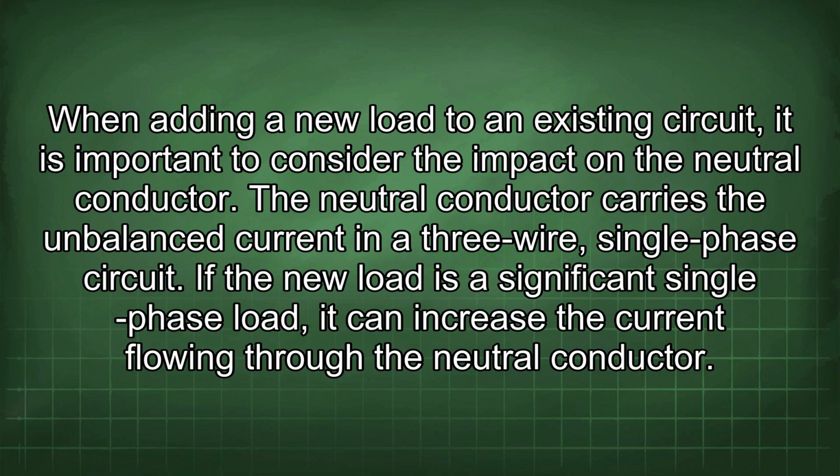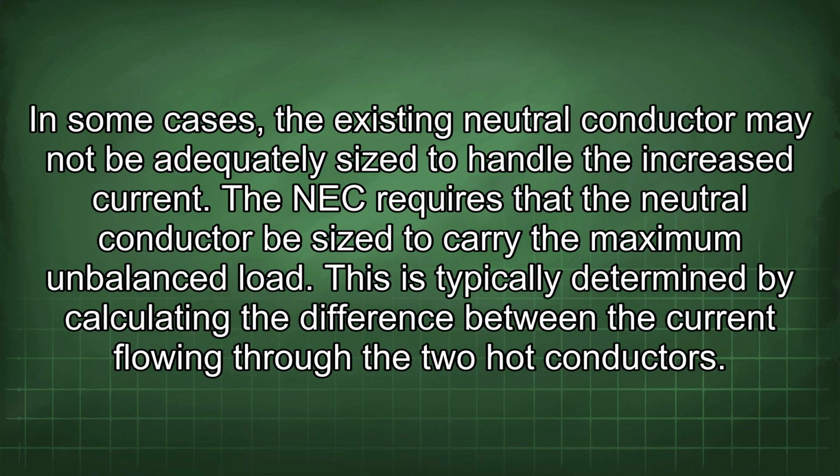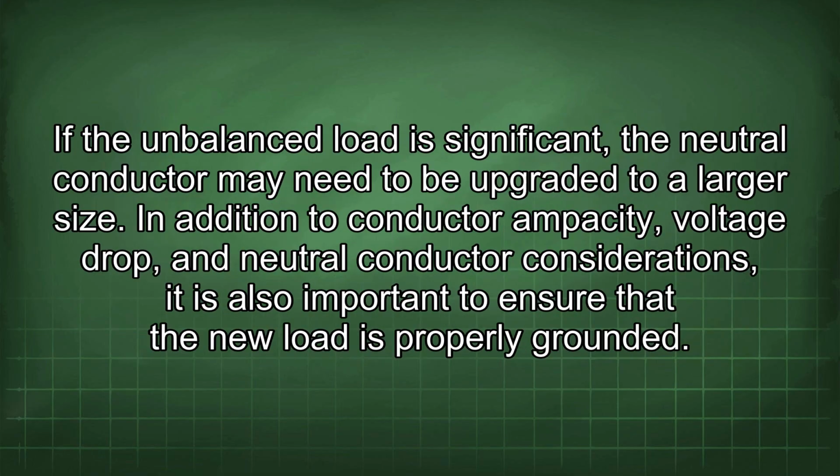If the new load is a significant single-phase load, it can increase the current flowing through the neutral conductor. In some cases, the existing neutral conductor may not be adequately sized to handle the increased current. The NEC requires that the neutral conductor be sized to carry the maximum unbalanced load. This is typically determined by calculating the difference between the current flowing through the 2 hot conductors. If the unbalanced load is significant, the neutral conductor may need to be upgraded to a larger size.